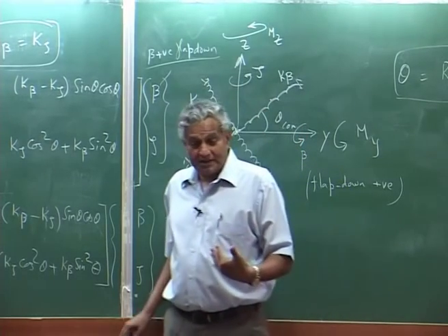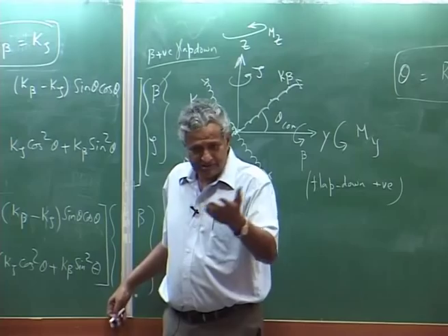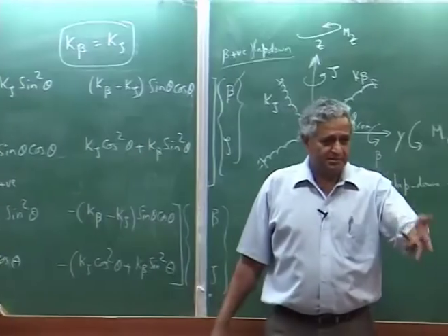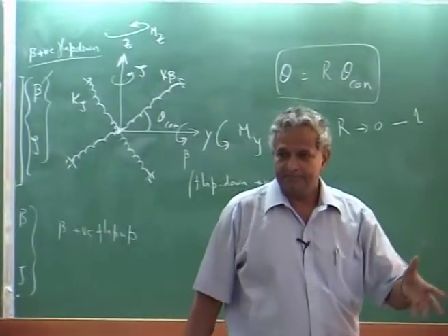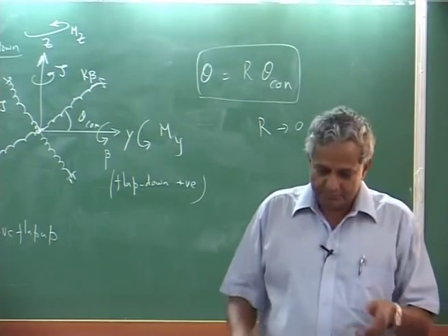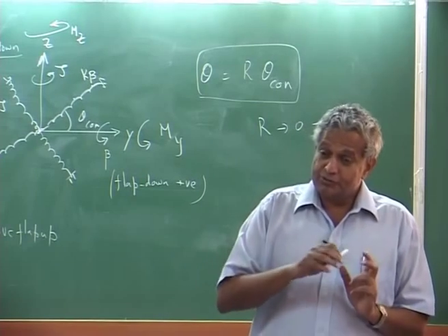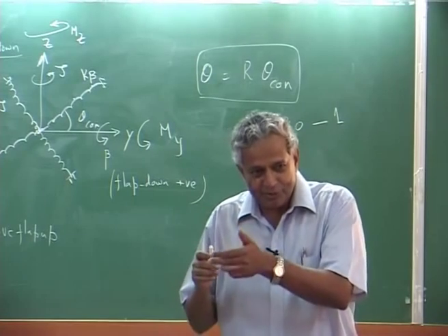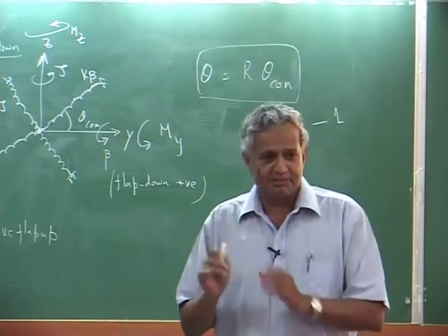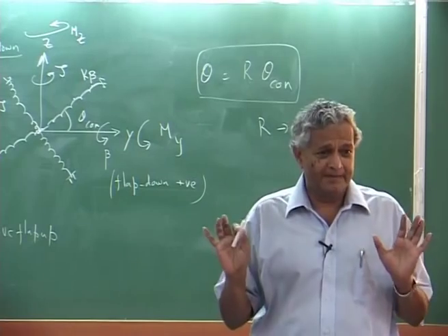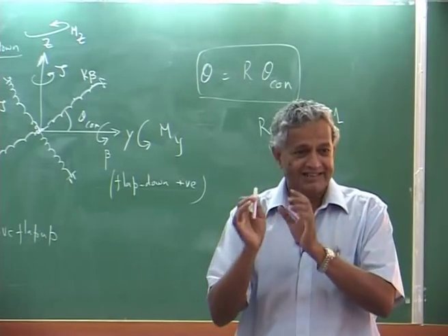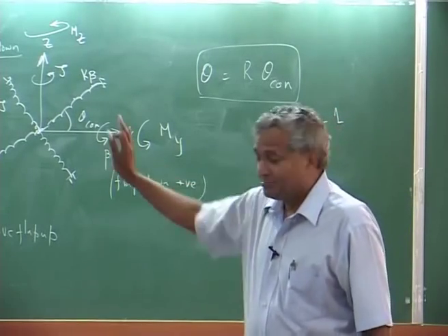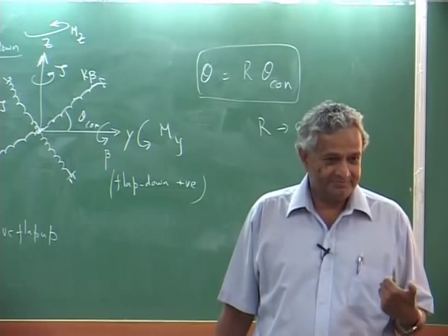But now you realize, for an elastic, hingeless blade, I can't avoid this coupling, because by construction I am getting that, and the pitch bearing is inboard. Now you say I do not want the coupling, then can I make the blade at the point where it flexes such that the flap stiffness and lag stiffness are the same? That means it should be a square section with the same distribution of material at the point where it is flexing. If I can design that, this coupling is removed. Okay.